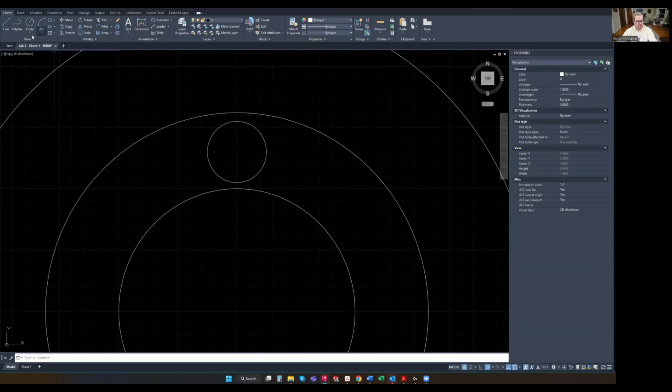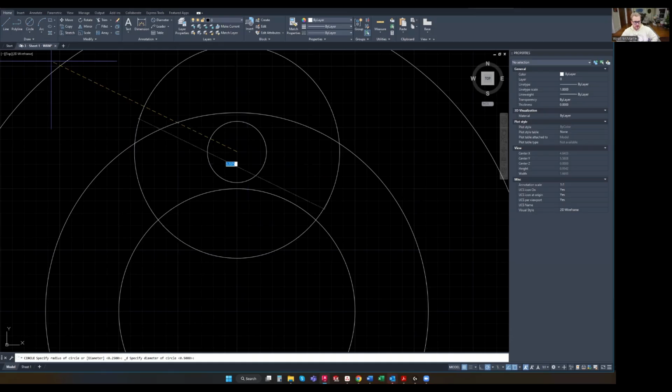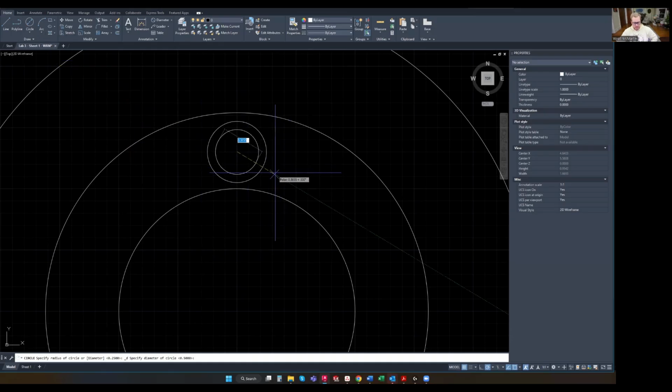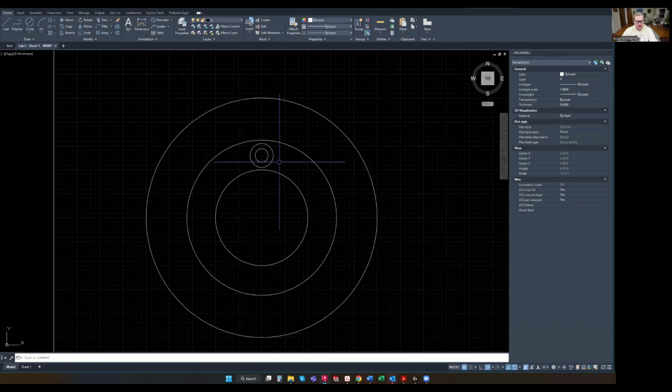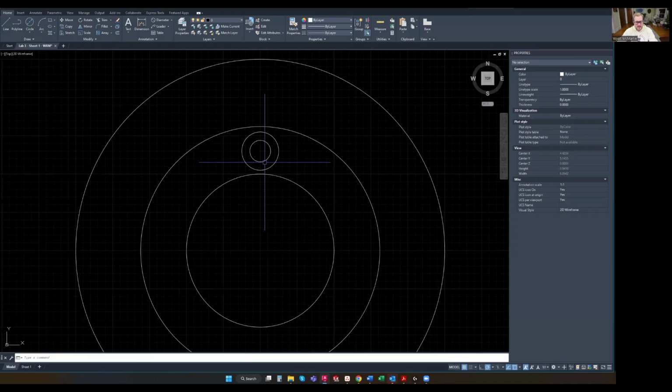You grab your center diameter tool again, so you can type C, enter, and then remember use the D, enter, or you can just click center diameter, hover over the edge of that circle, the perimeter, grab that. And now we don't have to click D, enter here because I entered the command through the draw toolbar, just clicked center diameter. And this circle is going to have a diameter of 0.281. Just like that. And from here, we're going to go ahead and execute a polar array.